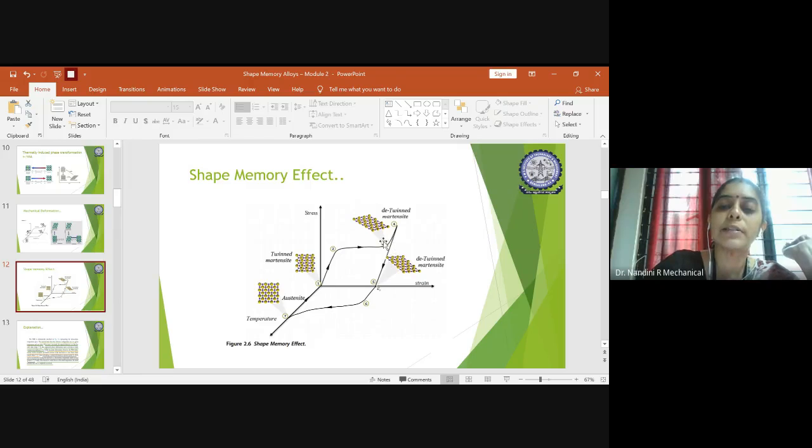Irrespective of applying high temperature, it comes down, which means it is coming back to the elastic behavior to regain its original position. Hence you will be able to understand the optimized temperature at which you get the highest stress level. At that point, the twinning of the martensite phase comes into the picture. That point is called detwinned martensite. This is what happens from slope 3 to 4.